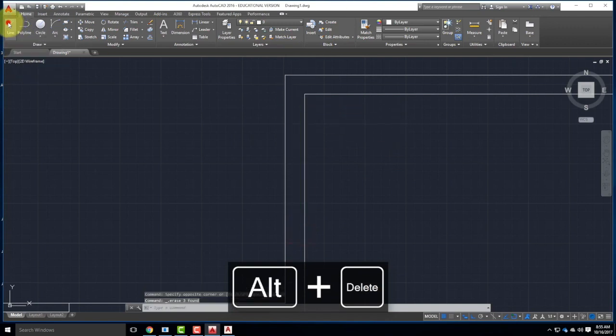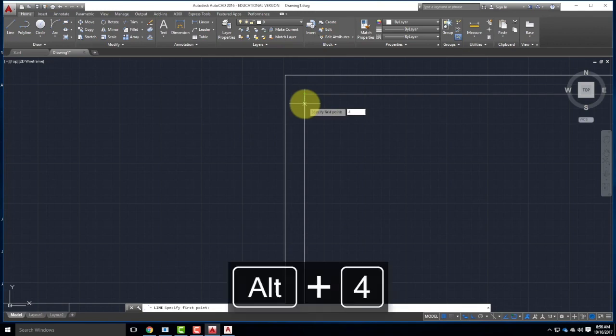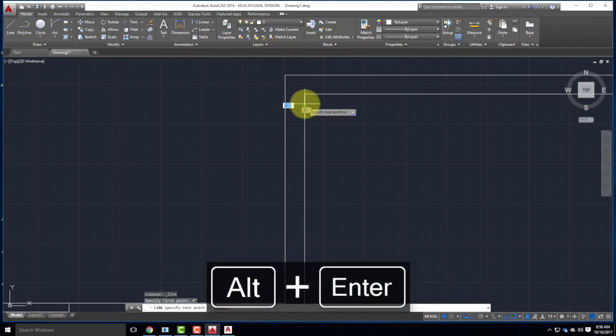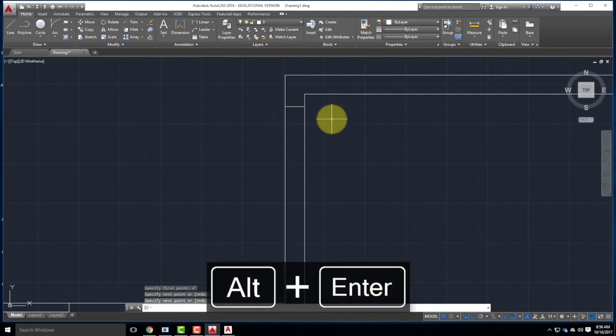Or I could go to my line tool and I could hover. I'm not clicking. I could hover over that point and then move my mouse down. And see how I leave that little green plus and then I get a dotted line? I could specify a distance here. So I could say 4 inches. And that then starts a line that's 4 inches from where I referenced the point. And I could draw a perpendicular line there.